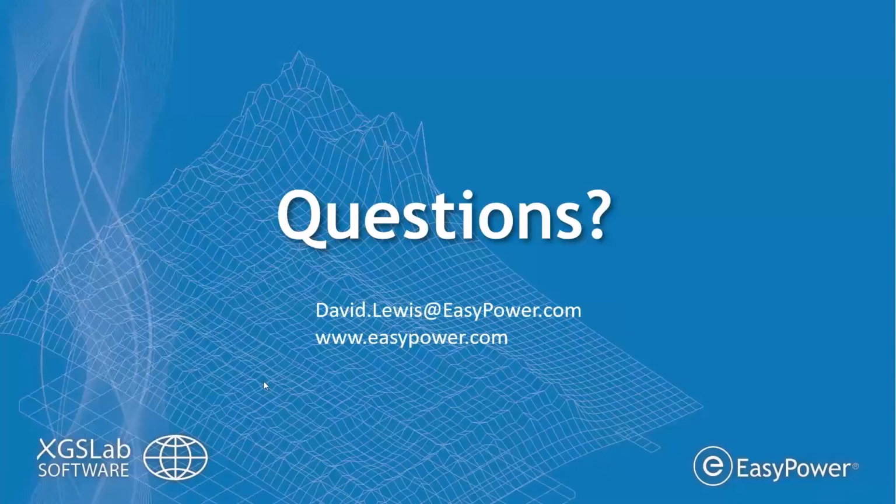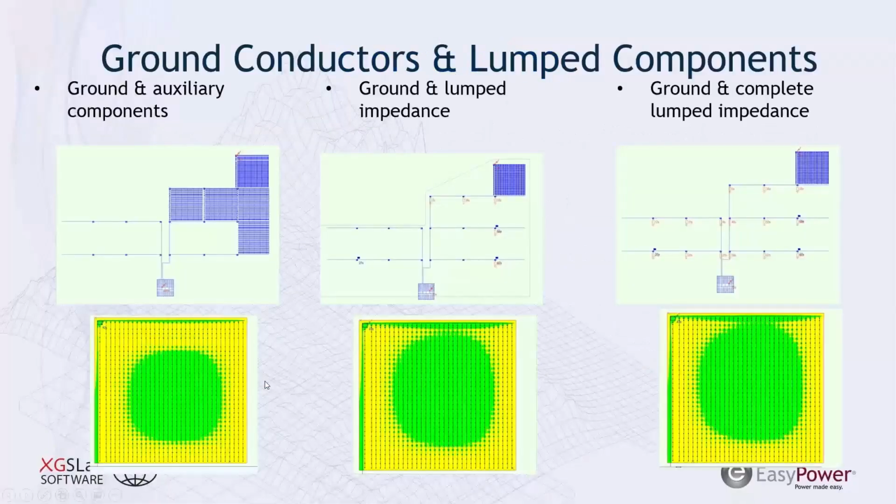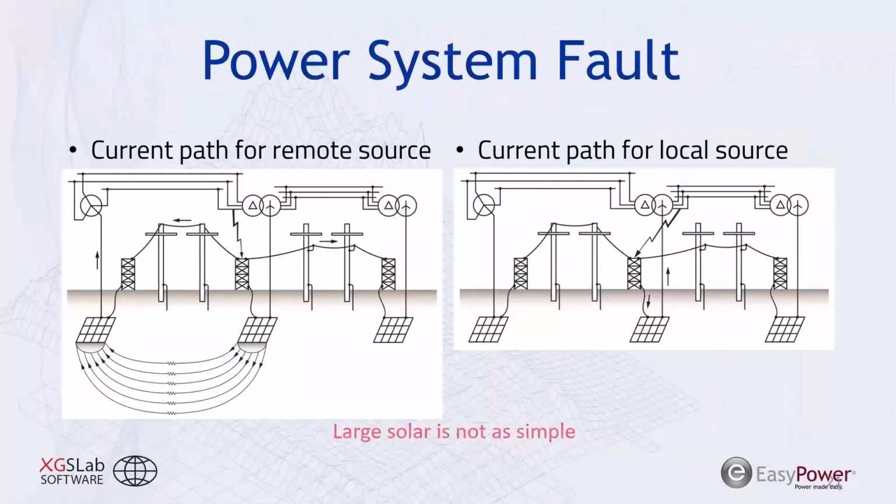One of the questions that came up, in the fault current split portion here, is just re-elaborating on how the ground potential rise is going to occur versus, I guess, its relationship to its source. So what we have illustrated on the left is my power system operating normally, and then we'll say a fault happens, and so the current is going to try to return to its source wherever it may be. In reality, our power system is going to have multiple sources, but back at wherever your source is, you're going to see a ground potential rise at those locations.